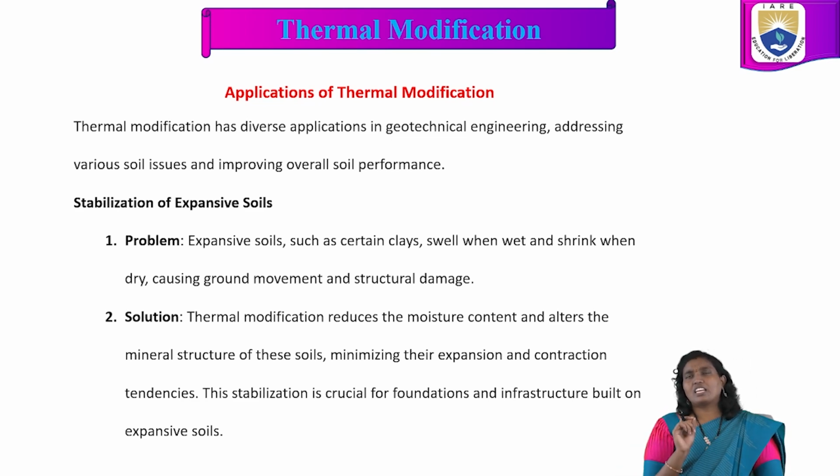Thermal modification reduces the soil moisture content and alters the mineral structures of the soil, minimizing their expansion and contraction tendencies. This stabilization is crucial for foundations and infrastructure built on expansive soils.